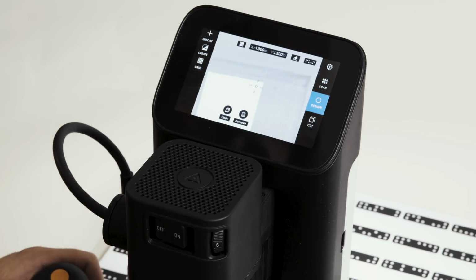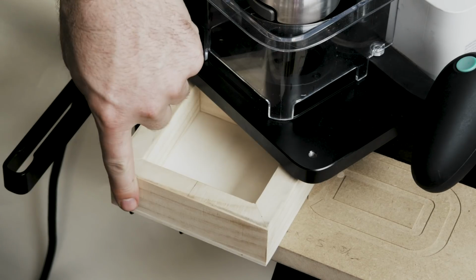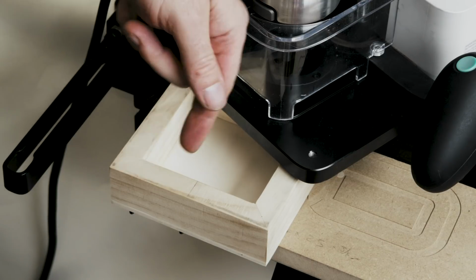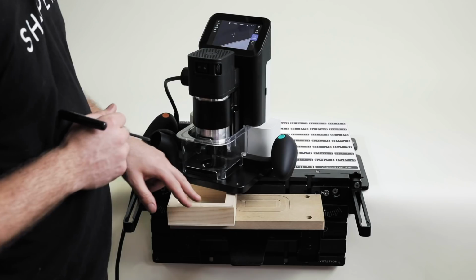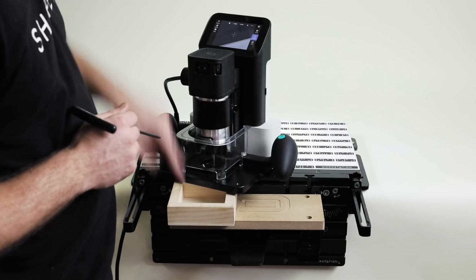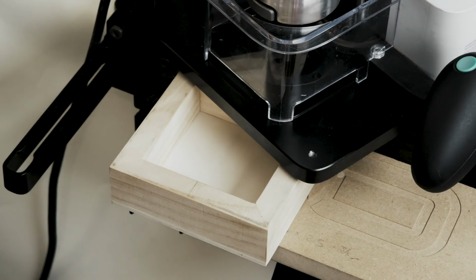So now we're going to move on to a hybrid approach. So this will be our hybrid probing method where we do 2 physical probes and then a visual probe using the point of a cutter to reference this pencil mark. We're not going to use the screen scanned raster image of this that we see in our workspace. We're going to literally look at the tip of our cutter. So we'll go through the motions of that now.